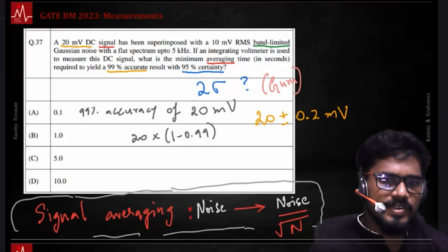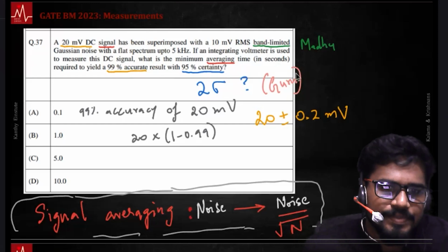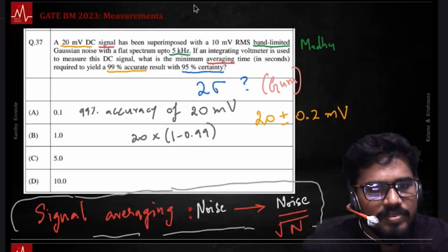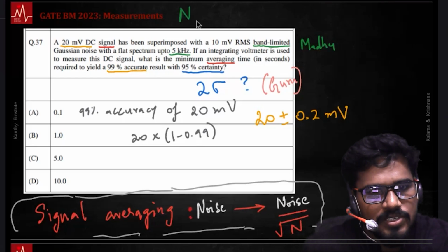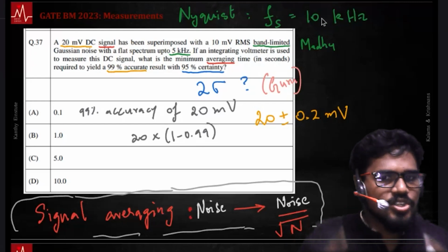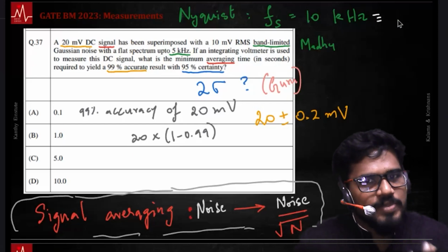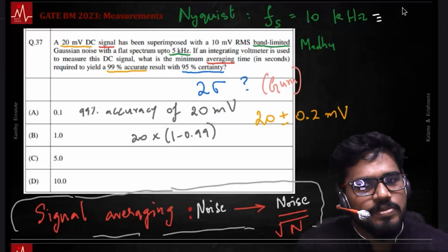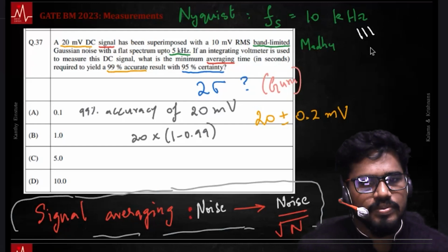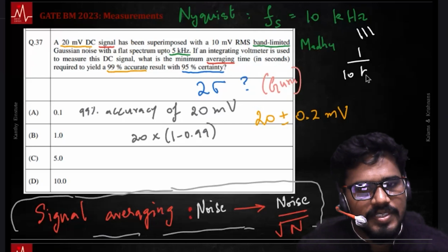Does anyone recognize that? Now I should give credit to Madhu Walala. You should sample at twice the spectrum bandwidth. If the signal is at 5 kilohertz, this goes back to Nyquist, Fs is 10 kilohertz. The rate at which you're getting signal should be at least 10 kilohertz. The minimum distance between one sample and the other is 1 over Fs. That gap is 1 over 10k seconds.